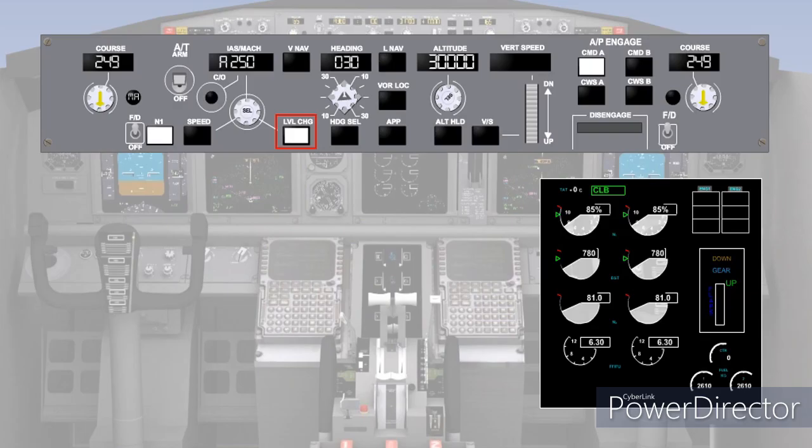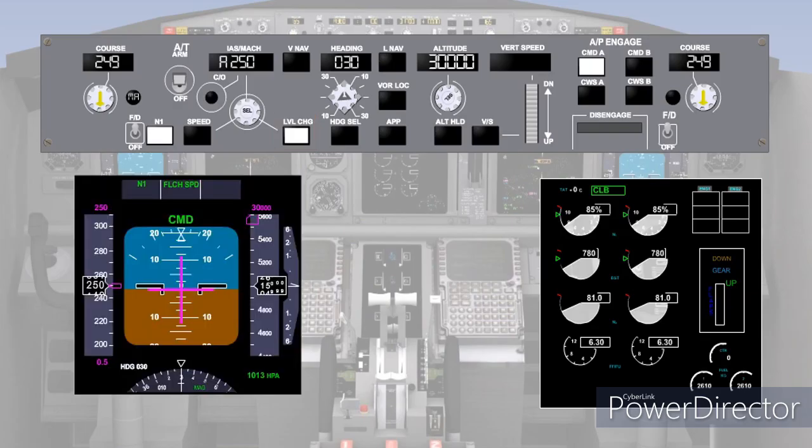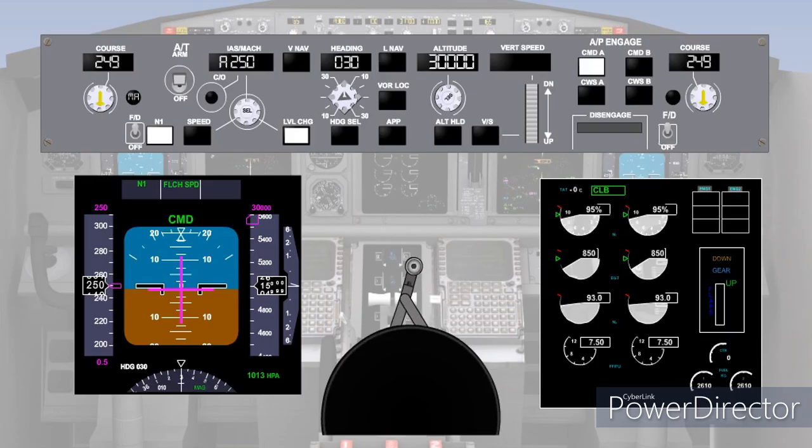Flight Level Change mode engages, and Altitude Hold mode disengages, indicated by Flight Level Change speed being the enunciation in the Pitch Flight Mode Enunciator window. Simultaneously, the autothrottle will change from speed to thrust mode, indicated by N1 or thrust in the Flight Mode Enunciator. The autothrottle will now advance the throttles to give 95% N1.